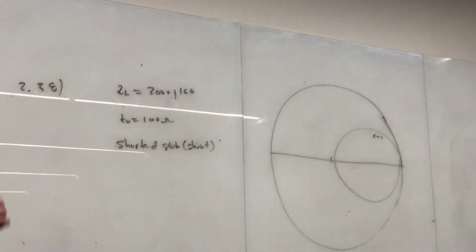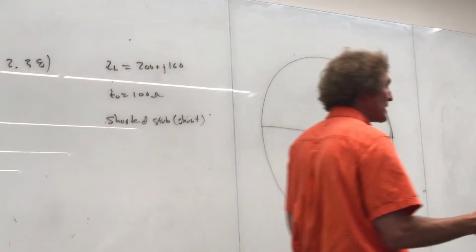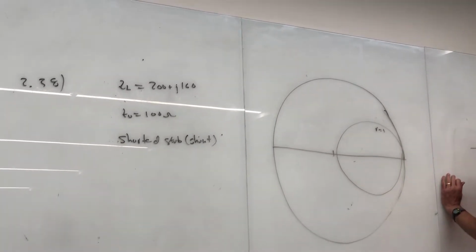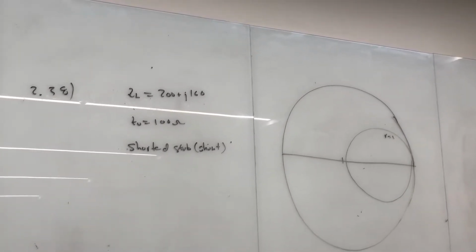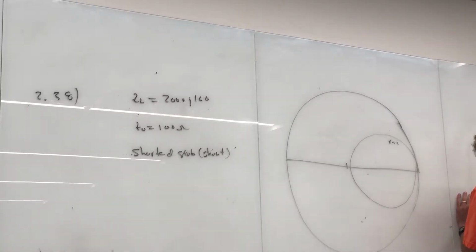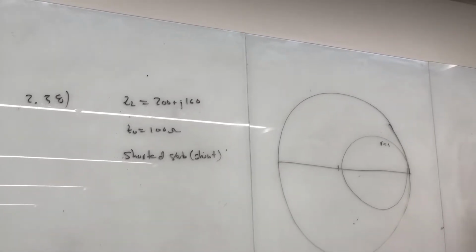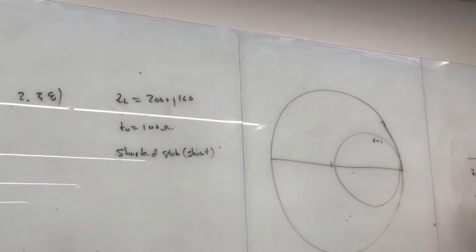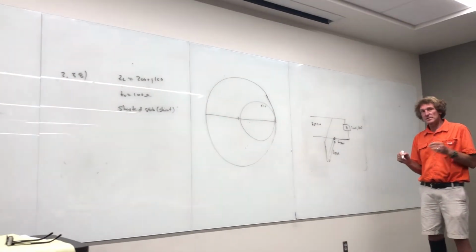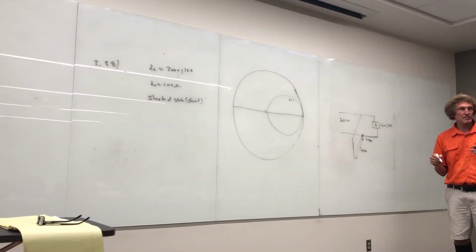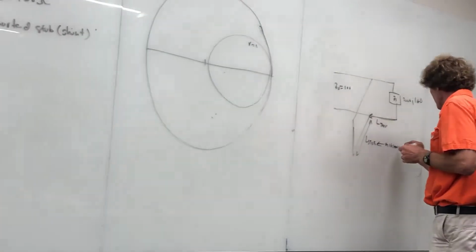So, if you remember these things, when you're doing impedance matching, the first thing is, let me sketch out what we're looking at here. We're looking at a load, some ZL that's 200 plus j160, and it's right now tied on to a characteristic impedance of 100 here. And they're looking at the distance L through, and L stub, or however it's called. He's looking for these 2 distances. But his stipulation is he wants the stub length to be minimum, right? So he wants this minimized. Minimum length here.